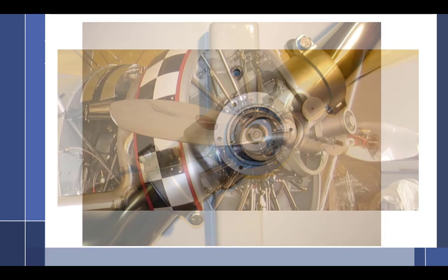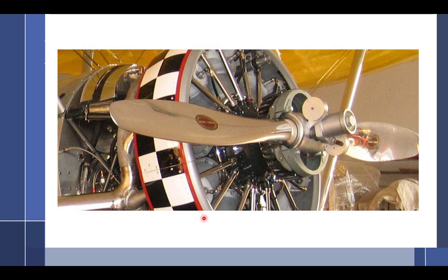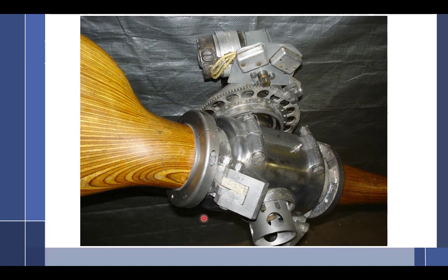What else do we have? This is, I think, my representation of a 2-speed propeller. A 2-speed propeller has 2 pitches, high and low speed. So it's like 2 gears. We'll talk about that. I think that's a Beech electric propeller. And this is not a constant speed, but a controllable propeller. And I'll write notes. We'll talk about all this in much more detail.